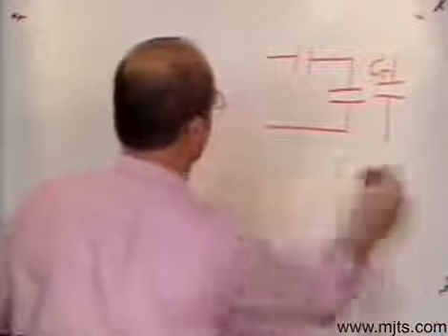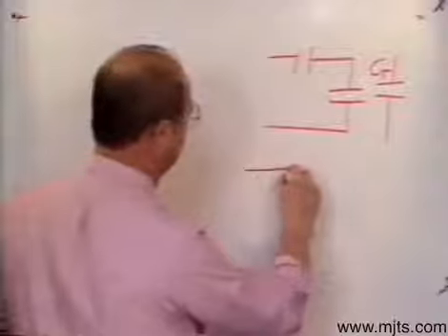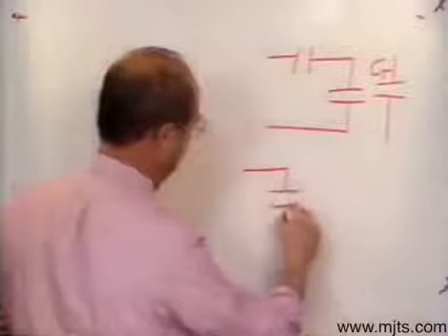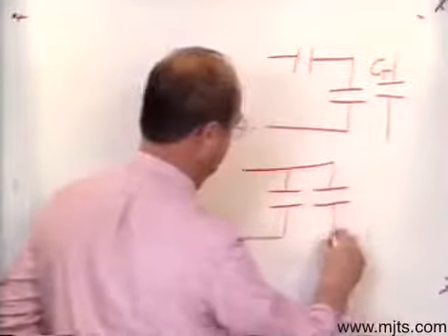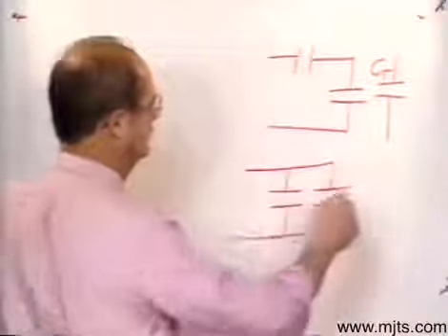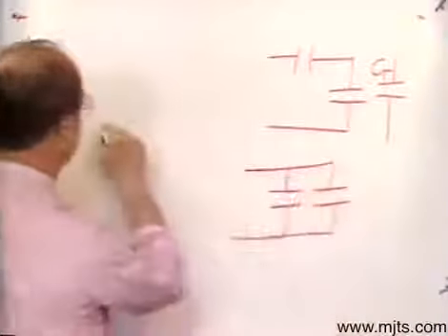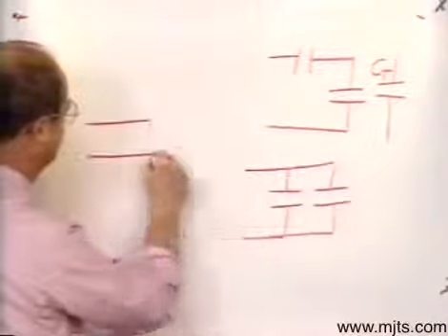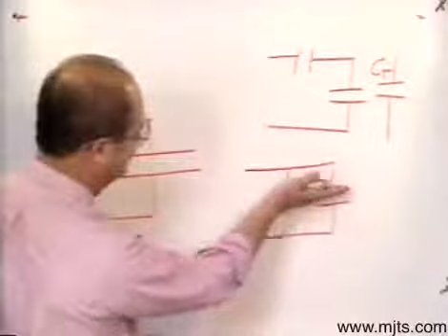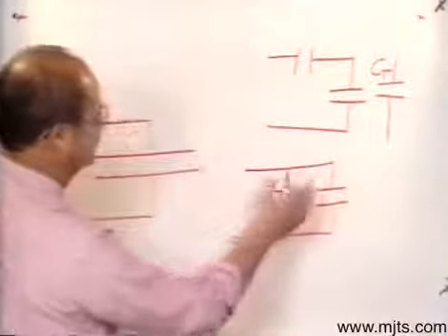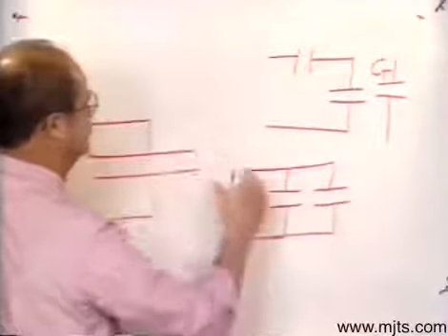Okay? Now, when I put them in parallel, if I have two capacitors in parallel, now what I'll do, I'll add them. See? To get my total capacitance, I would add them, because it's like one capacitor of twice the plates, you see. In other words, each side has more plate area. So now when I have them in parallel, I'll add their effects to get the total capacitance.